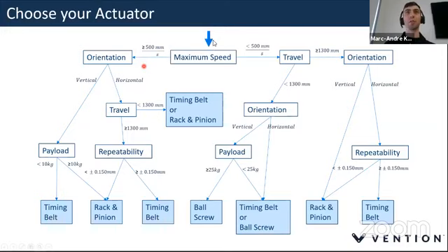All right, so starting from the top. Our application needs to be under a full cycle time of 85 minutes, but at the same time for 10,000 holes. So that doesn't tell us the speed itself, but we know that from one hole to the other, it's only 5 millimeters. So it's going to entail that the maximum speed won't be very high. The acceleration might be high, but not the maximum speed. So it's most likely going to be under 500 millimeters per second.